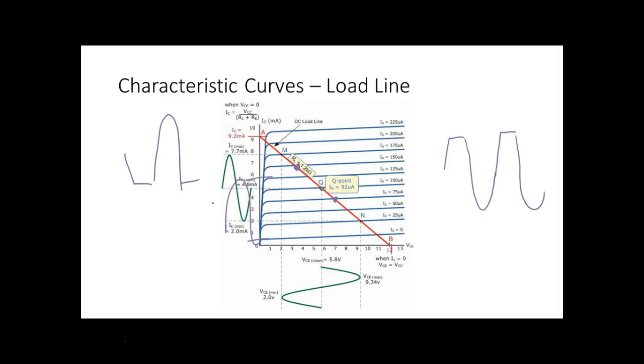So yeah, you could put resistors in series, and I would, but you'd still be dealing with tolerances anyway. If you wanted to hit it perfect, you would use a rheostat. Every resistor in there would be a rheostat, and then you could bias that sucker right in the center. But what are you doing now? You're taking an amplifier that might cost $2 to make, and now you make it cost $20 to get it in the center.